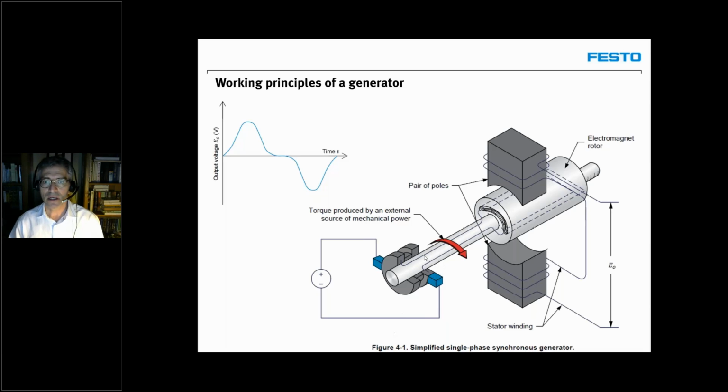So as we can see here, we have a rotor that is mounted on a shaft. The rotor is made of a coil of wire, and this coil of wire can be fed a DC current by the contactors here, the brushes, the collector that we have here. So as you can see, we apply a DC voltage to this collector, and this will send the current through the coil, which will in turn generate a magnetic field in the middle of this coil. And of course, this shaft is turning. So this is happening while the shaft is turning, so while the coil of wire is turning.